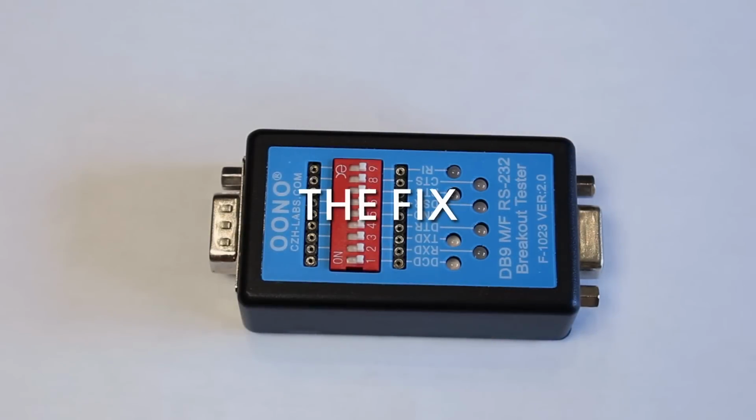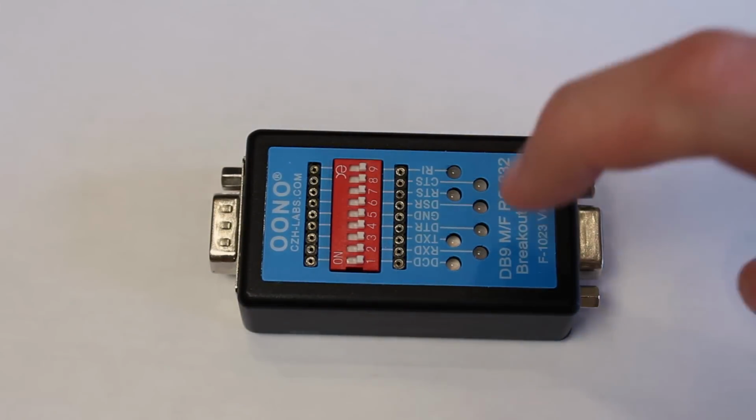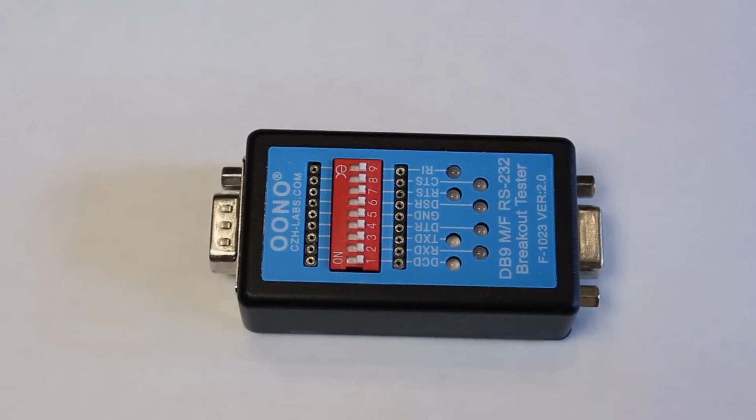A really quick and easy way to test this out is using this little RS-232 breakout tester. There's a female 9-pin on this side and a male 9-pin on this side, so it can just sit in between the MUX card and the cable going to the terminal. In the middle here, there's a 9-position DIP switch, and this can either turn on or off the signals passing through. Right now, all of the switches are off, which means no signals will pass through at all.